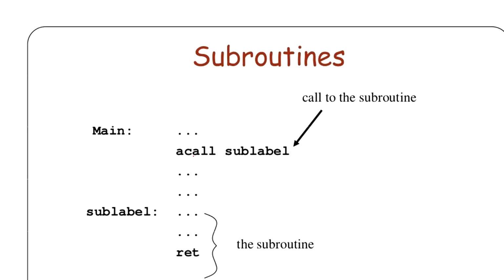In the main program, I call the ACALL. This is the label, what I mentioned. This holds an address, either 11-bit or a 16-bit address. Your program counter jumps to the label where it is specified and executes the subroutine program. And whenever a return is encountered, it returns back to your main program and executes the next sequence. This is how the execution of your subroutine works.